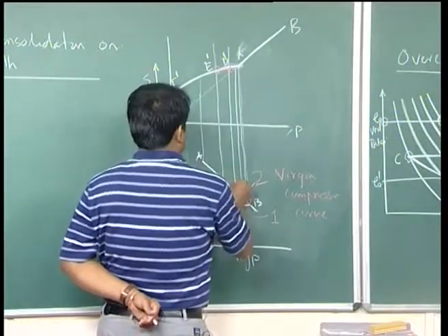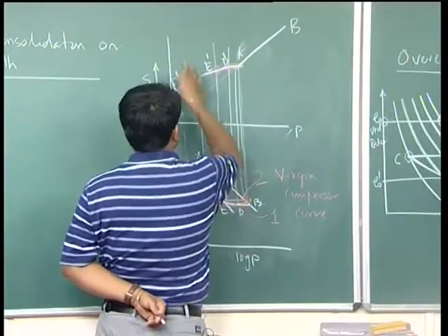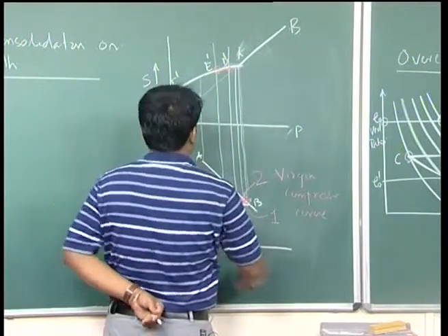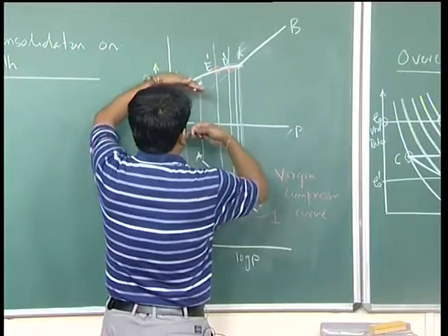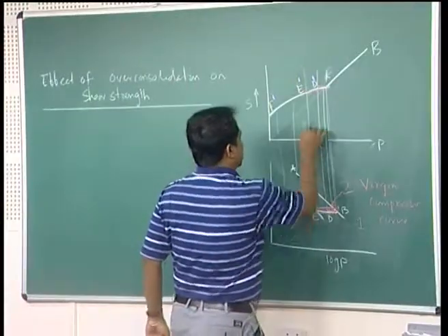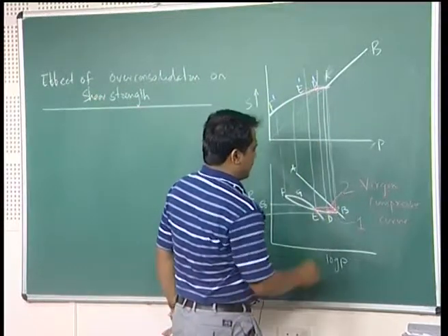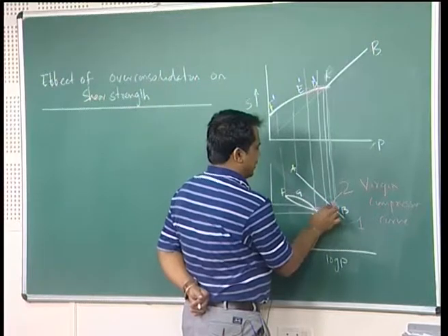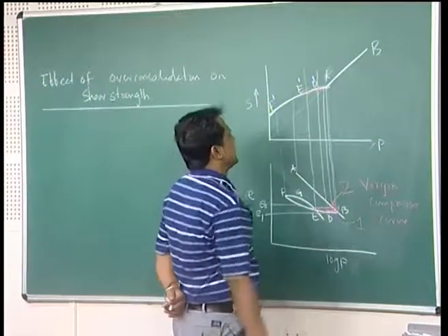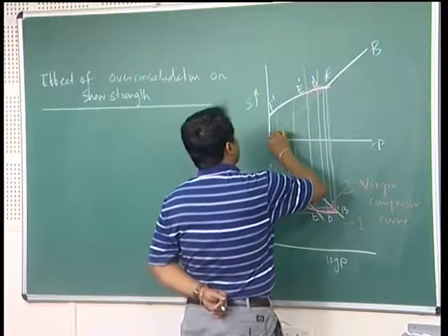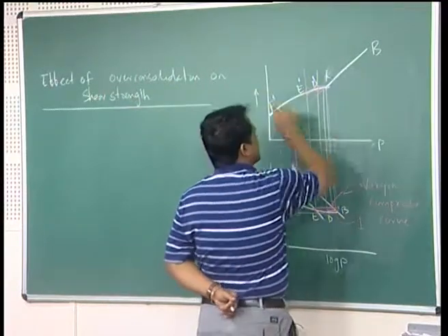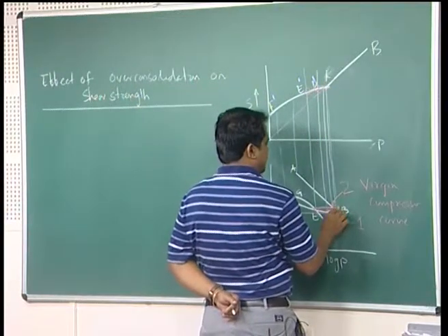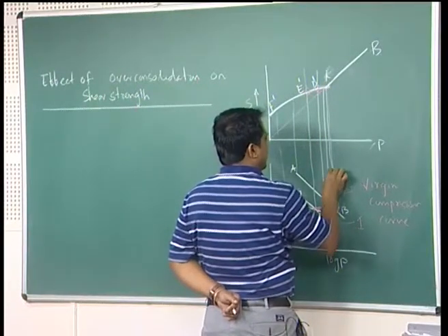So, this has been shear strength and P with this E versus log P, it has been plotted in the same scale. So, you extend it. Now, where it intercepts the 2 points A and B of your virgin curve, it has been extended. Now, where it intercepts in shear strength versus log P, this is the intercept point, this is your point 1.